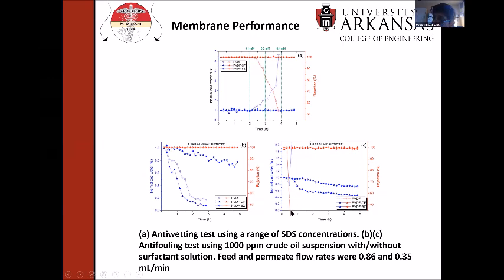So what happens is first oil starts to adsorb, it starts to lead to fouling, you get a decrease in flux, but at the same time SDS is also adsorbing, and so very soon you get wetting and breakthrough and the membrane fails. For the two modified membranes, you can clearly see the rejection for sodium chloride remains high at close to 100%, but you see a definite decrease in flux, and it is much more pronounced for the CF membrane. So again, the BZ membrane, when you have that hydration layer, is resistant to fouling by oil, which leads to a much higher flux and productivity of water.